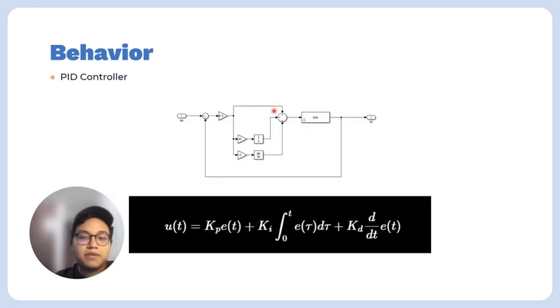For the PID controller, we're implementing PID controllers for each motor with specific gains, being Kp, the proportional gain, 6.3, the integral gain being 1 over 0.06, and the derivative gain 0. These controllers regulate the motor's speed to minimize the error between desired and actual speeds.